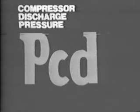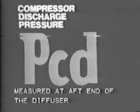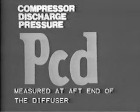The term PCD refers to compressor discharge pressure. It is measured at the aft end of the diffuser in the turbine bearing support housing.